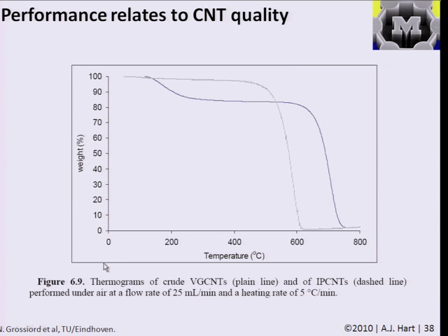So in principle, this is telling us that that higher conductivity in the final case beyond the percolation threshold is also influenced by the fact that those nanotubes had a higher intrinsic structural quality. Incidentally, the nanotubes from the forest also had a higher content of amorphous carbon that burns off at lower temperature, in fact about 10%, whereas the industrially made nanotubes were a lot purer, but the conductivity of the forest nanotubes was nevertheless higher in spite of this difference. So here's an example of a case where those two differences in network properties based on two types of nanotubes might be related to other characteristics of the material using other characterization techniques.